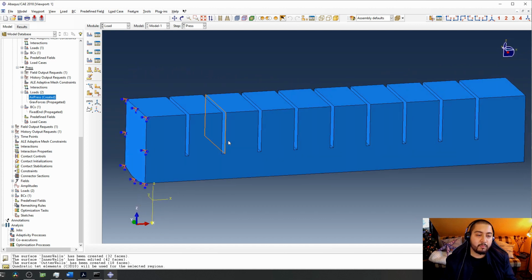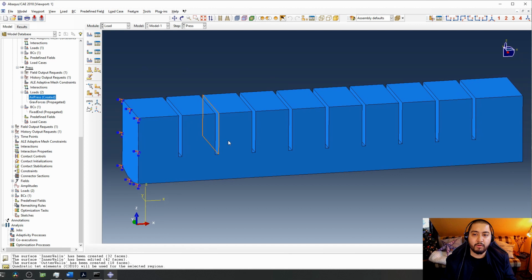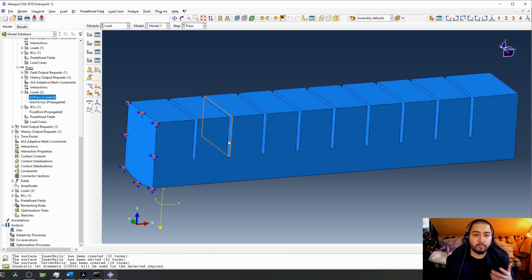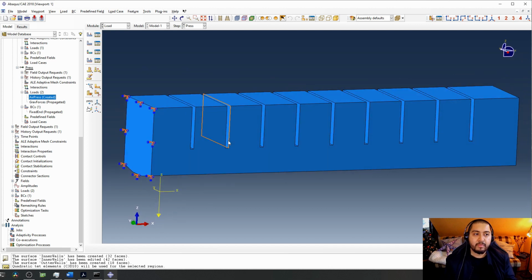And if they have contact, we want to know, and we want to compute this contact as well, in order to predict maybe failures or too much contact that can lead to a failure, or just to really know when they have contact with the force. So I really recommend you to always try to define interaction properties properly. To do that, we go first to the interaction properties.